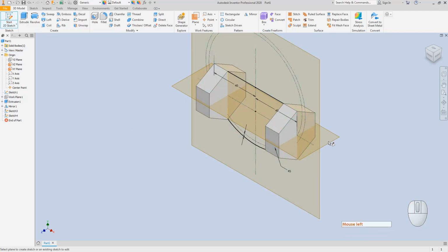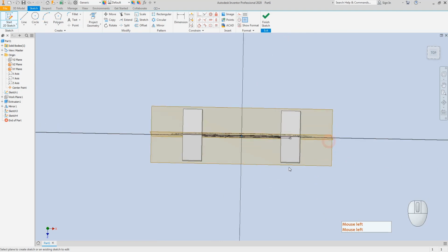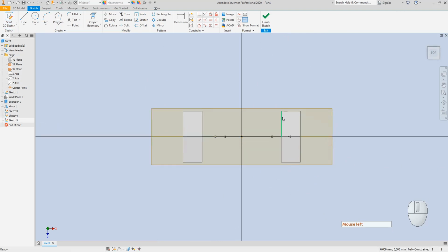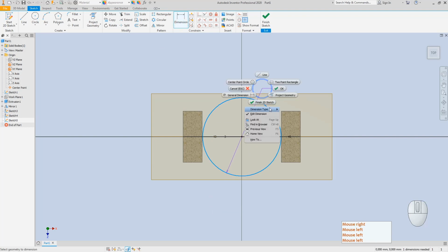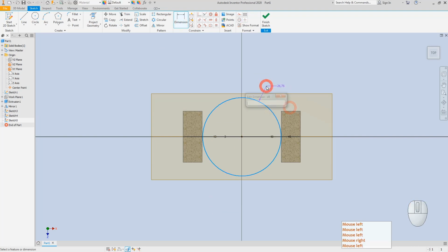The next thing, I'm going to start a new sketch on the XZ plane. And this time, with the F7 tool, I can just remove everything between my point of view and the sketch that I'm working on. The next thing I'm going to create is an arc shape which has a dimension with radius 55.